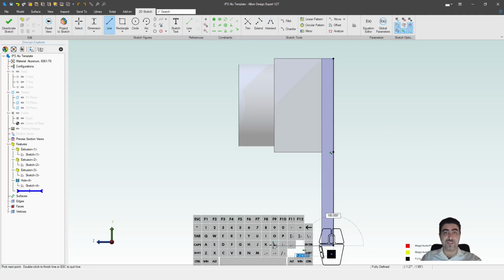Why? This is a complex session, right? Errors here cost. So you slow down. When you need to, you slow down. So 1.125. Again, this is not a dimension shown in the print. It's one I calculate. A, 3-point arc, remember that? Again, before I do anything, I just type a dimension and enter. The arc is still selected. Before I do anything, type the dimension and enter.